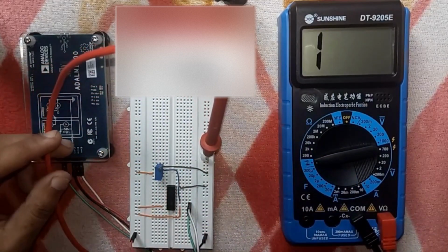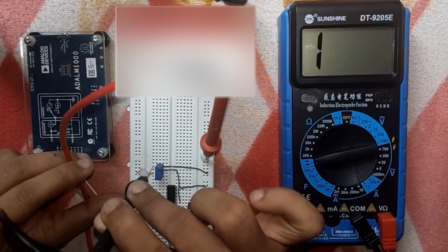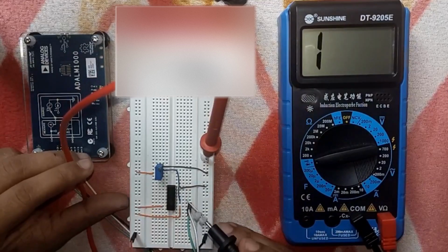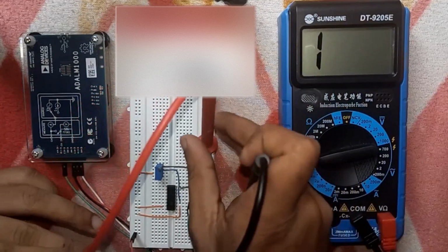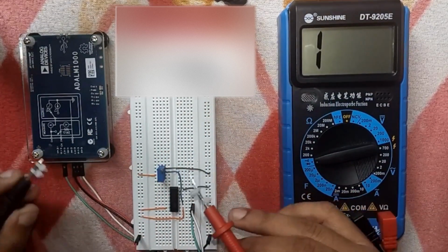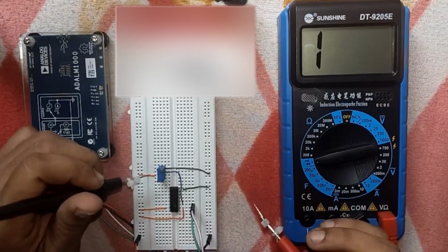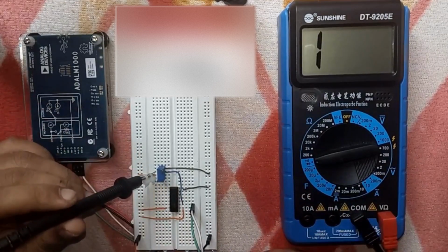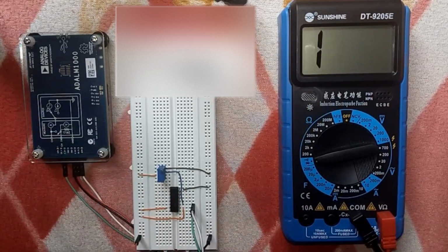So now we have to check the ground connection. Let's check the ground connections, which are connected to this pin of this potentiometer and pin 7 of this IC. Yeah, okay. So now another continuity check, of this blue wire, which connects the middle pin of this potentiometer with pin 2 of this IC. As you can see, all wirings are fine. So now we can easily perform the experiment.